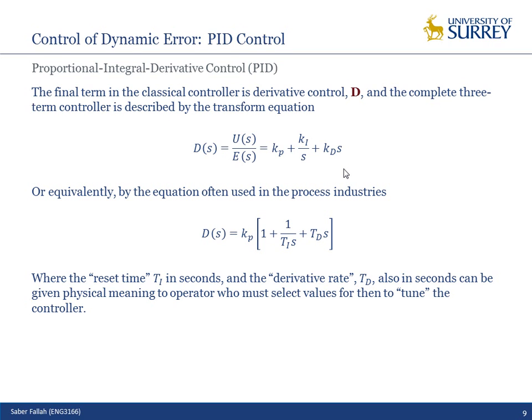So far we understood why we need to use the proportional controller or PI controller, proportional plus integrator controller. As we saw from the example, we can improve the performance of the first order system well using the PI controller because we can work with two parameters, damping ratio and natural frequency of the system. But if we have a second order system, we can't deal with all the coefficients of the characteristic equation. If steady state response is enough for us, PI most probably is good.